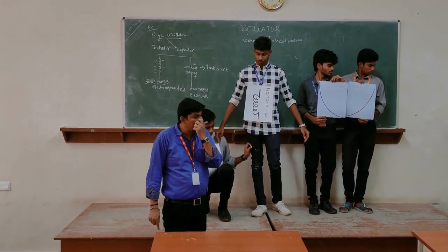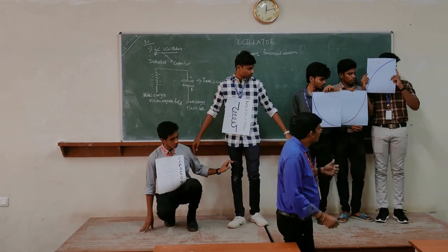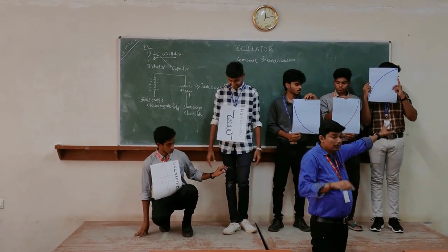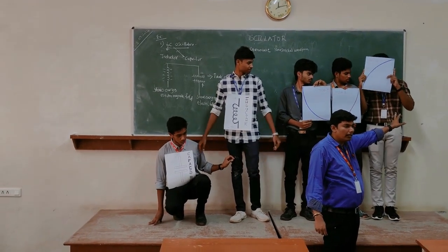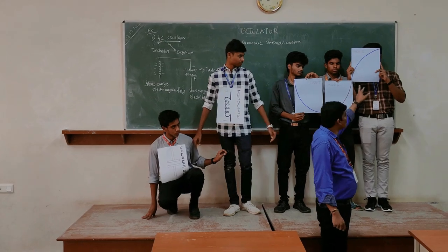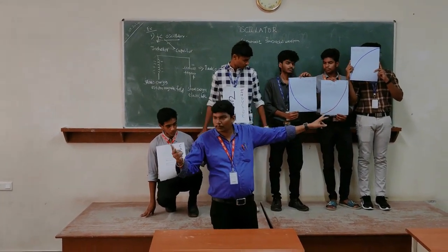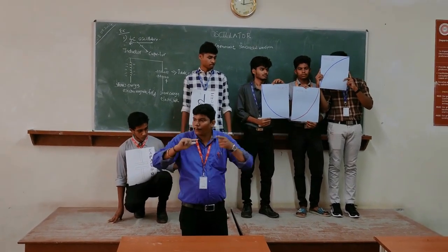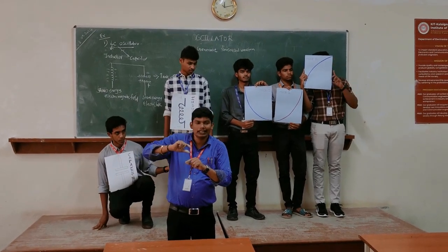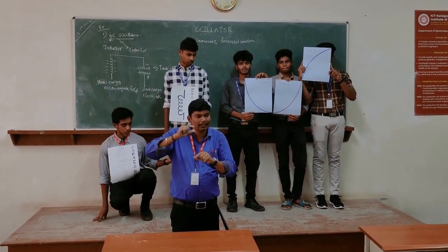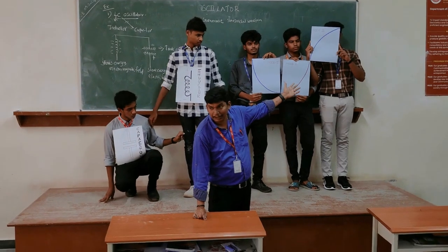This is the operation of mode 3. What happens now? The capacitor is going to charge. Right? That is the mode 3 operation. So from B to C, you can see the back EMF from the inductor. Whenever it produces the back EMF, what happens? Polarity is changed from minus to plus. So the oscillator's output waveform will now be in the opposite, positive region.